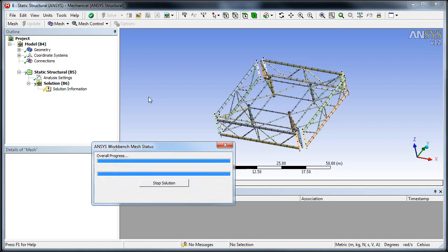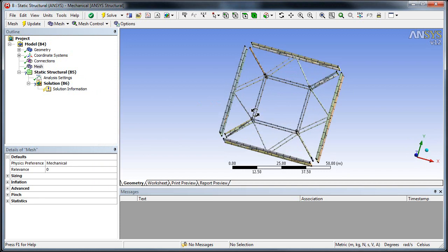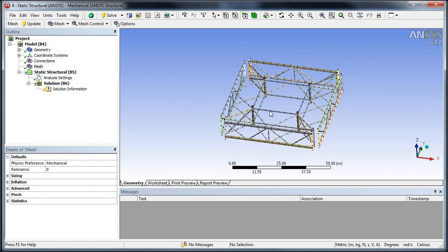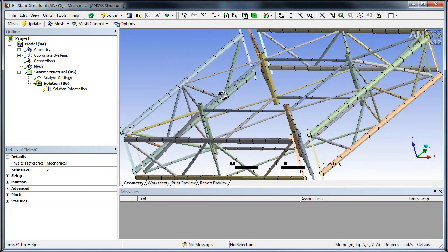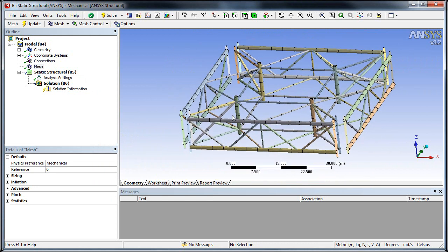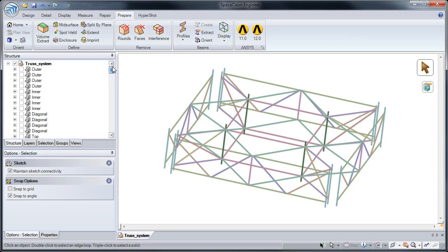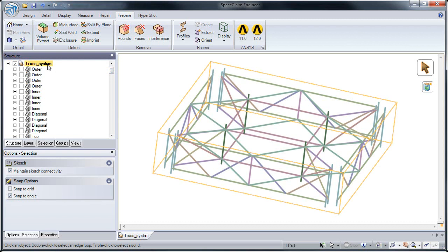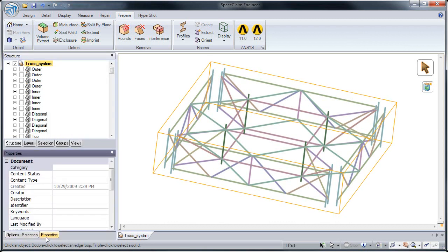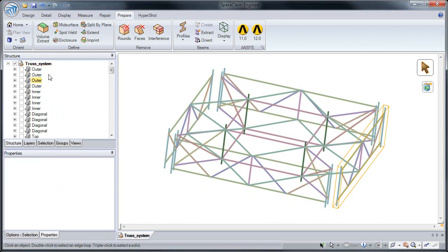And one thing that we can also look at is our mesh. Notice that our line bodies are now shown in ANSYS with some of the thicknesses associated with them. So here I hope you've seen how SpaceClaim can be used to extract solid bodies from these parts. And also remember, if you'd like them to share topology, definitely change our shared option from false to true.